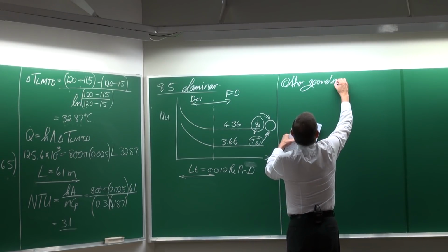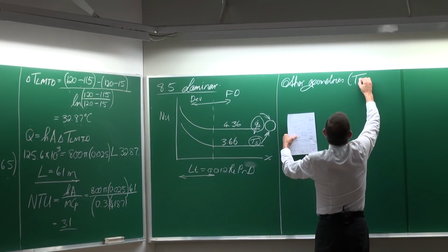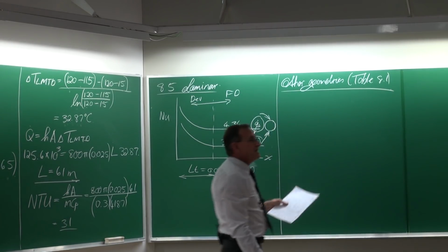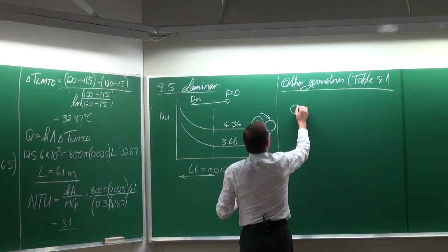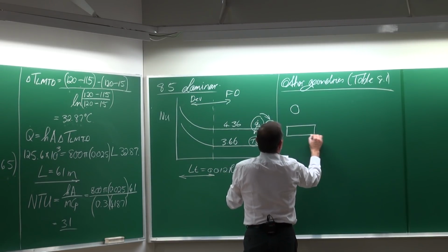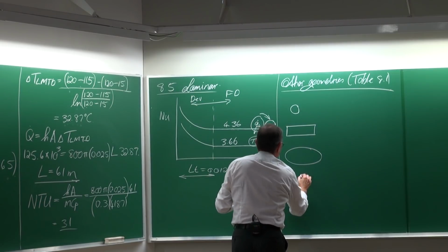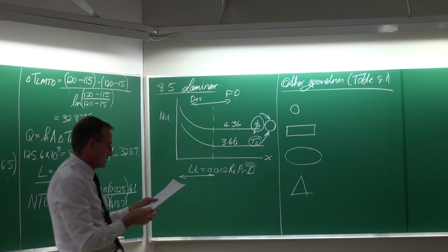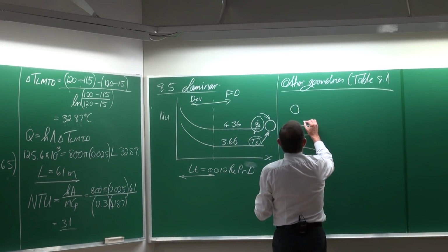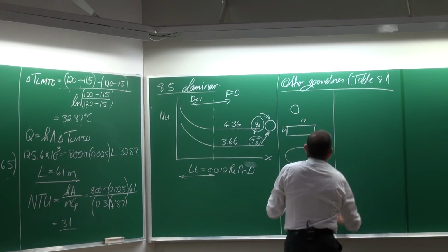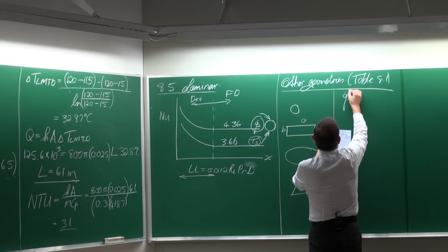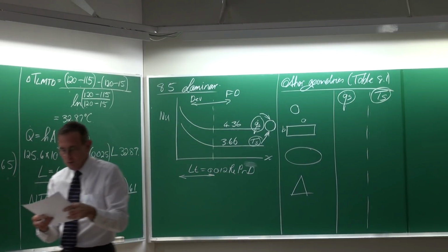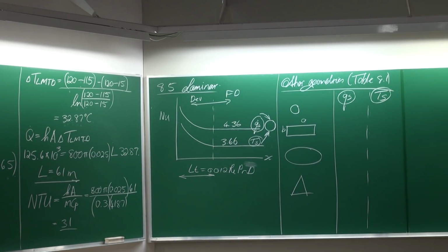And they are given in table 8.1. In that table, different geometries of tubes are given. Four or five of them. Again, it is just samples. There are many more available in literature. And depending on the aspect ratio, the values are given for a constant heat flux and for constant surface temperature. For laminar flow, all the Nusselt numbers are given there.